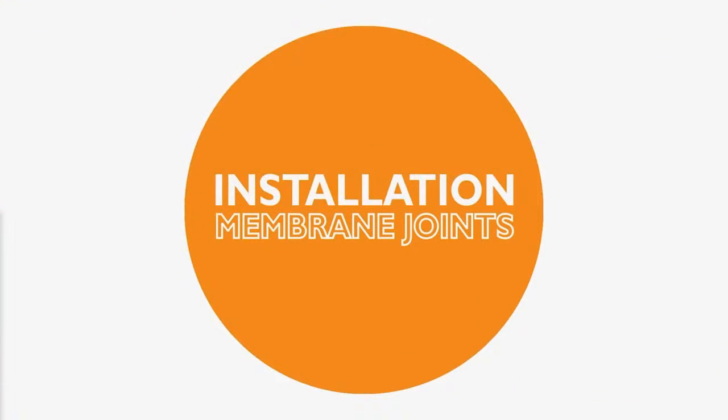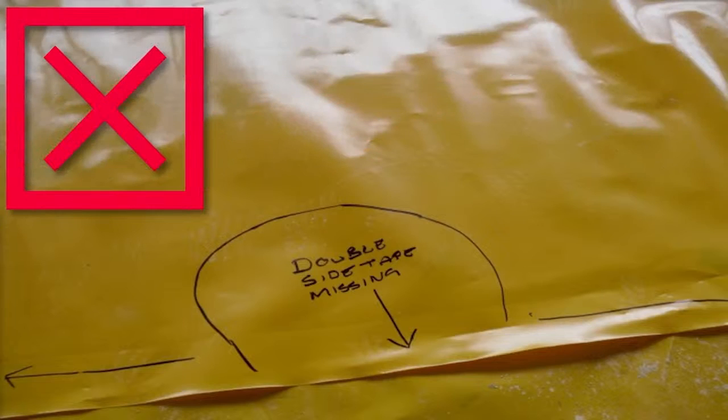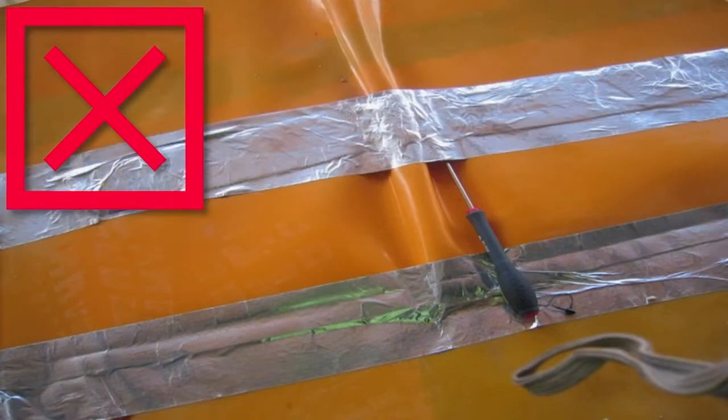Another detail found everywhere is the simple membrane joint. Apparently simple enough, joints between adjacent runs of membrane commonly cause problems. The most obvious problem is the missing sections of sealing tape, creating a path for gas to bypass the barrier, but tape joints can cause other problems. Here we can see that the tape run has not adhered to the membrane where the membrane is not sitting flat on the substrate.